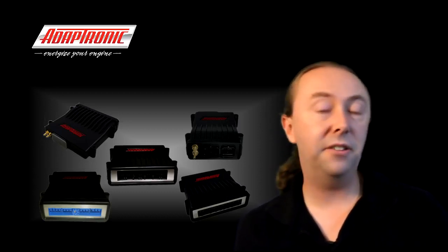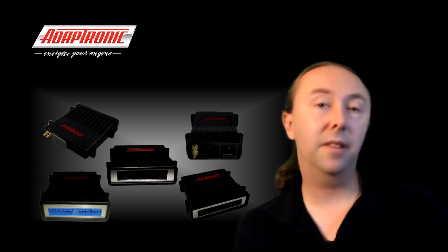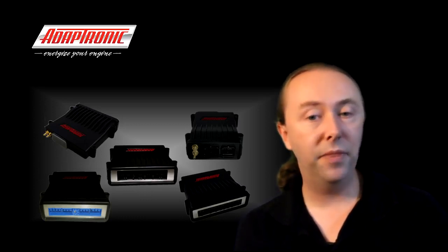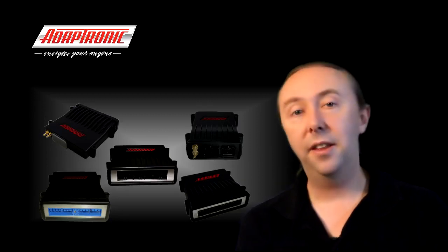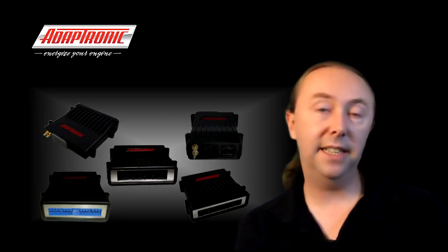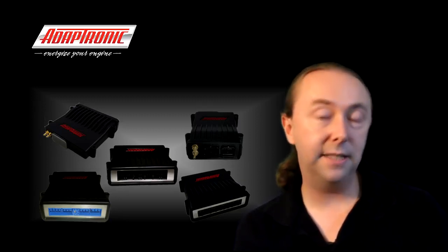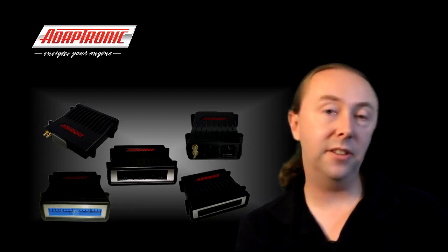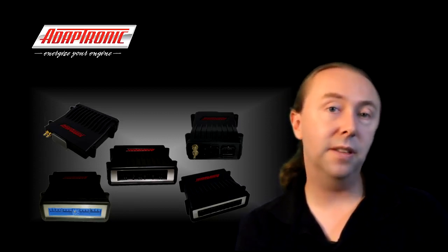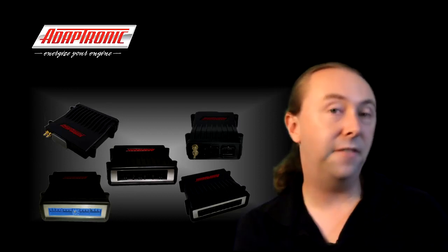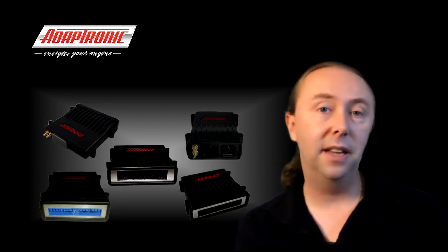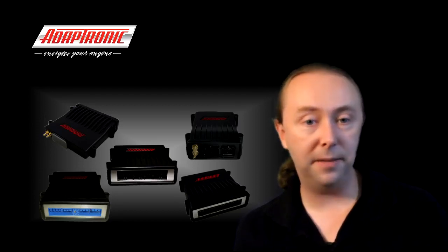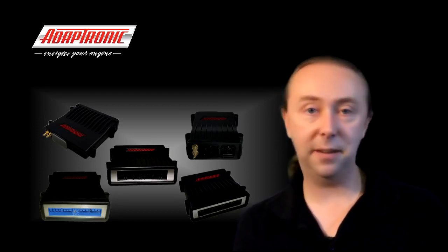So if you've got a higher battery voltage, then you will end up with a higher current through the injector. And also, a part that might be a little bit less obvious is that the higher the voltage, the higher the dI/dt, which is how fast the current increases. So in other words, with a high battery voltage, the current through the injector will increase at a higher rate, so faster, than with a lower battery voltage, as well as the fact that the eventual current flowing through the injector will be higher as well, not including any current control done by an ECU.